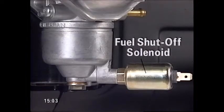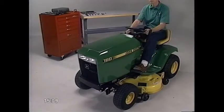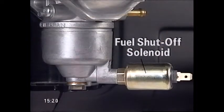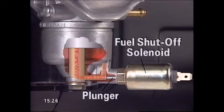Some models also feature a fuel shutoff solenoid to prevent afterbang, the detonation of unused fuel in the muffler that happens after the ignition is turned off and the engine is winding down. When the ignition is on, the solenoid plunger retracts, allowing fuel to enter the main nozzle. But when the ignition is turned off, the plunger extends, blocking the flow of fuel to the main nozzle.